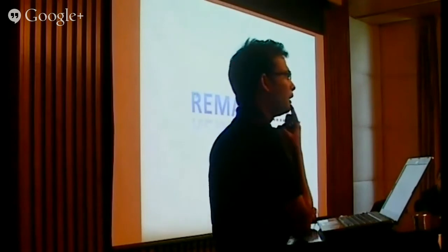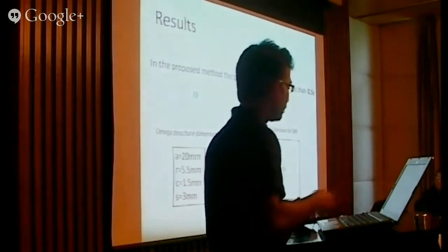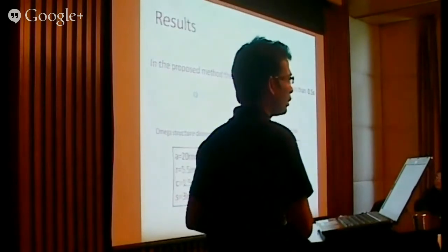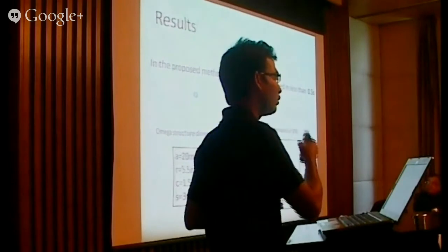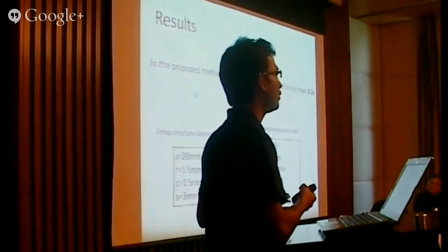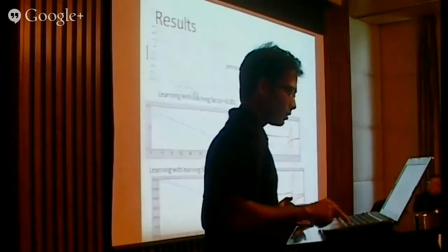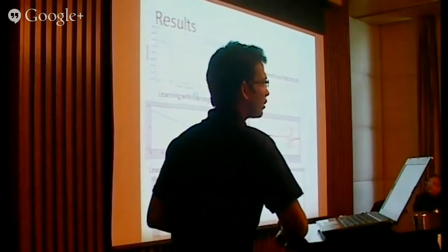Yes, no, it is not independent of frequency, because I have shown you these dimensions I got from the equivalent model. Using these dimensions, I have to put them in the Lorentzian form available to calculate the permeability. And that formula itself has a variation with frequency, and for this addition of frequency I get this curve.